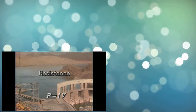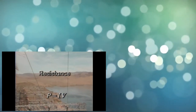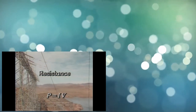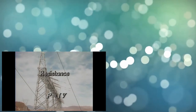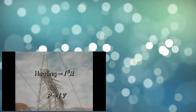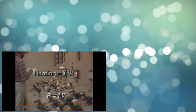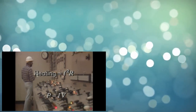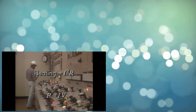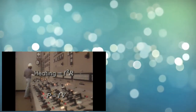Remember, the power cables have a certain amount of resistance, and the longer the distance, the bigger the resistance, because a cable's resistance is proportional to its length. And of course, passing current through a resistance causes heating, which is equal to current squared times resistance. This is wasted heat. For the power company and the consumer, that means a certain amount of energy won't be available at the other end.